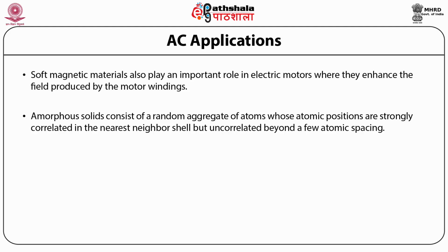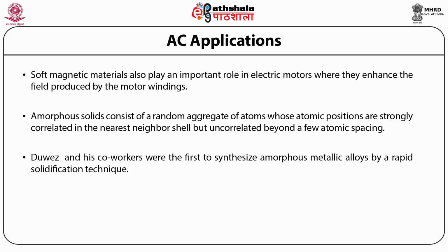Molten metal and metallic alloys invariably crystallize in their equilibrium crystalline structures when cooled below their freezing points. Duwez and his co-workers were the first to synthesize amorphous metallic alloys by a rapid solidification technique. This pioneering work initiated a spurt of research activity on synthesizing and exploring the exciting new phenomena exhibited by various amorphous metallic alloys. Amorphous alloys can be obtained through two diverse routes.